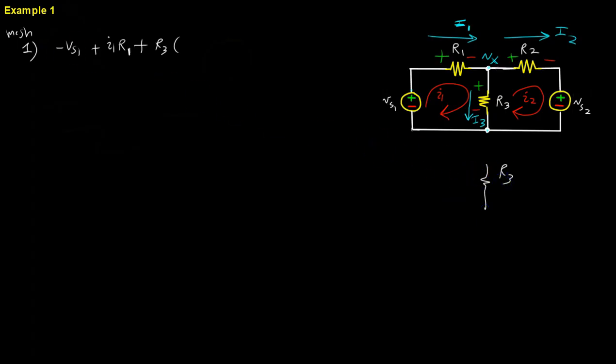What you have here is two mesh currents. One is going clockwise, so it would look like this, I1. The other one is going clockwise in the other loop, and what that gives you is that it's going to go upwards like that. So that's I2. If you've defined the sign convention to be in this manner, plus up top, minus on the bottom, what that means is that the net current is going to flow this way, which is I3.